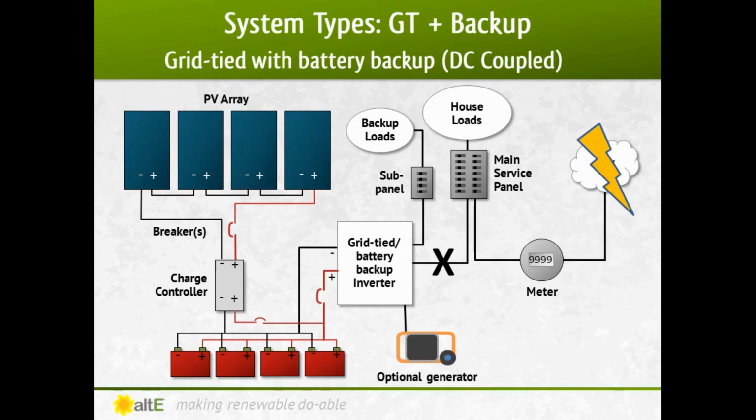These systems also have the option of having a generator to charge the batteries when needed. The advantage of this over just a generator system without a battery bank is you can just briefly turn on the generator to charge the batteries and then turn it off. This saves you fuel and allows you to silently run the critical loads at night.